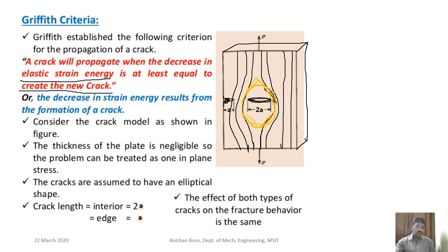So how much strain energy will be decreased if there is a crack? That we can estimate. You know the expression of strain energy: it is half into stress into strain. That is strain energy per unit volume, right?